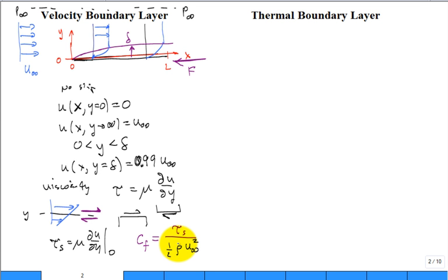The 1/2 is basically bringing a fluid to rest. And when you bring it to rest, it'll actually boost the pressure. And that pressure is called the dynamic pressure or velocity pressure. They're different names, stagnation pressure. Think different ideas there, but that's now dimensionless. And so you can plot C sub F as well as tau sub S, the shear stress at the wall, as a function of location. We're going to build on that. But I think that's enough introduction to the velocity boundary layer.